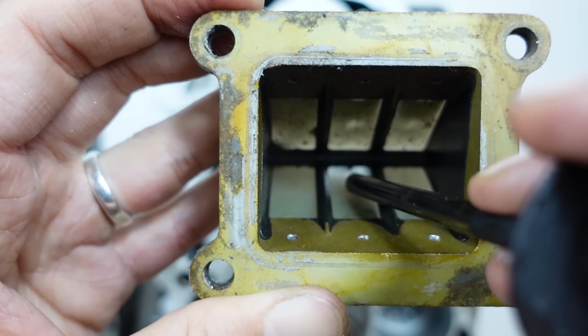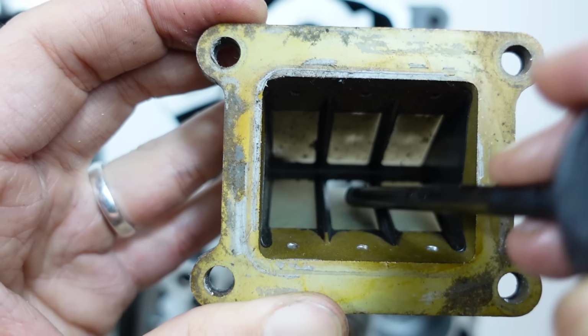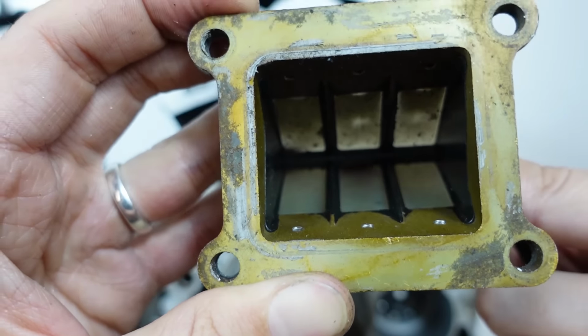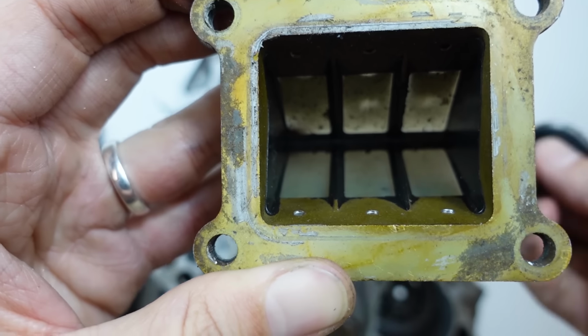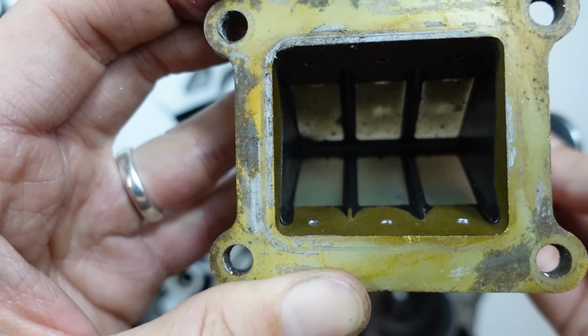The design of the reed valve is such that the petals can only open in one direction, and so crankcase pressure closes the petals and keeps the compressed air-fuel mixture from escaping back into the intake. Now, the elephant in the room that we have to address next is lubrication. If you have ever owned an engine in any kind of vehicle or appliance, then you probably know that lubrication is key for engines. Without the protective film of oil, metal-to-metal contact occurs and quickly leads to catastrophic failure.